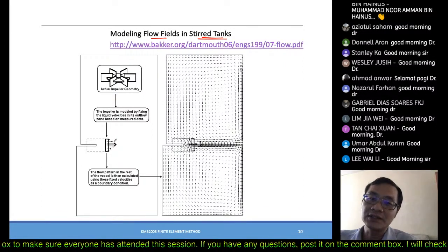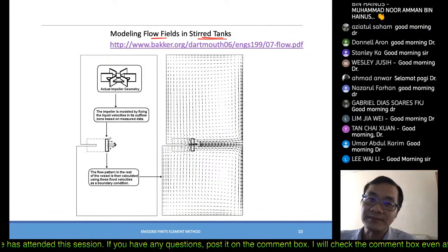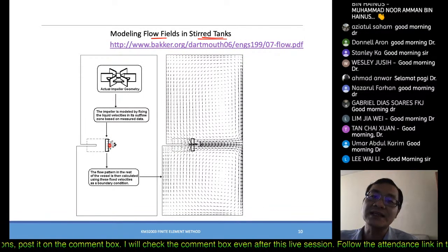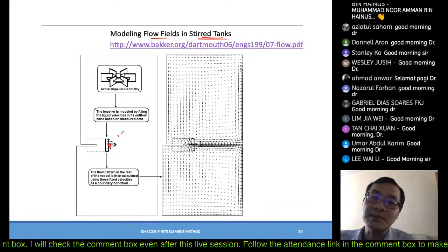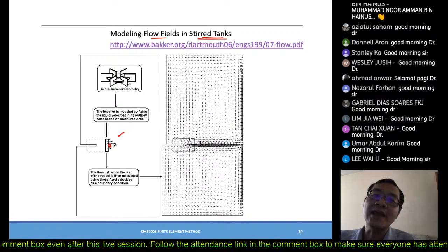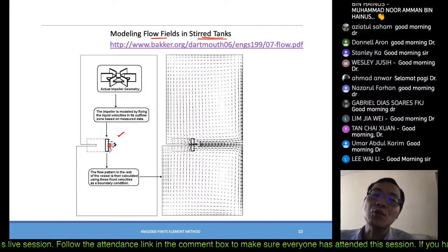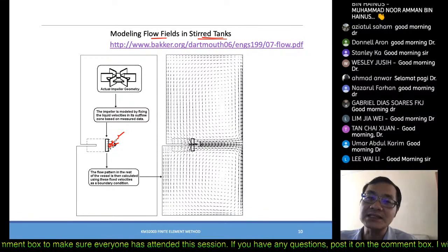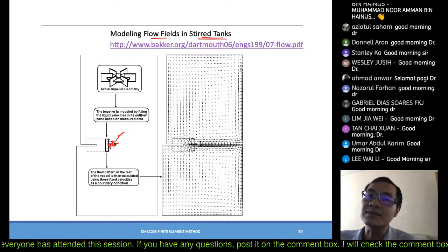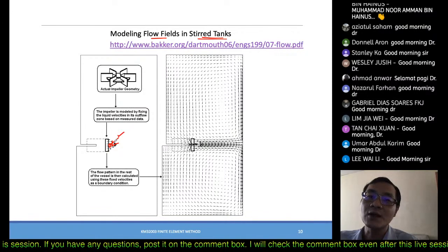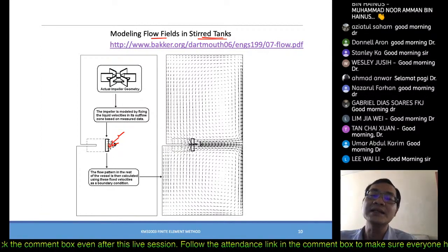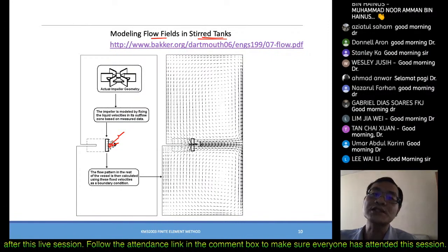And what he did is he measured the liquid velocity. Just do one measurement at the end of the tip velocity. Once he got this experimentally, this became his basis to run the simulations. That's why when a simulation starts, all these boundary conditions must be as true as possible. If possible, then you can run an experiment to start with.